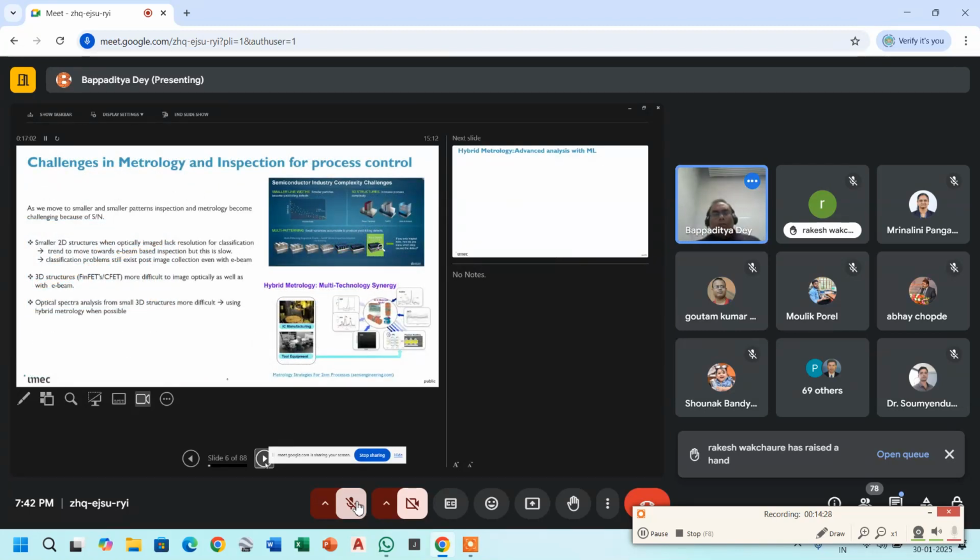Now, what are the challenges in metrology and inspection? I can imagine that you don't have the domain knowledge of this, so don't feel guilty. Just try to understand that metrology and inspection in process control is basically about keeping all these steps within constraints. We do metrology and inspection so that we can individually check whether something is going wrong or is beyond your expected spec. If yes, we have to do a lot of re-engineering and rework, and if not, we go to the next process stage, towards what you find in your mobile or your device, which is a packaged chip.